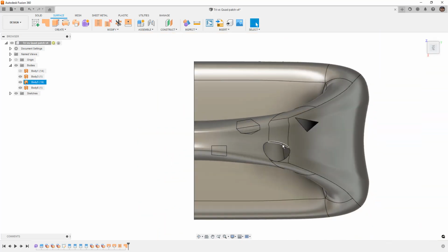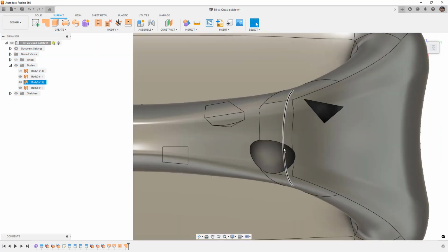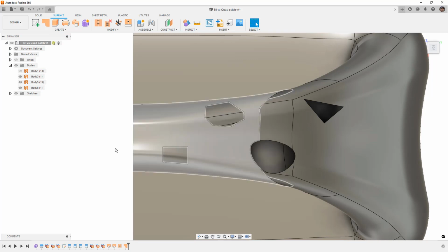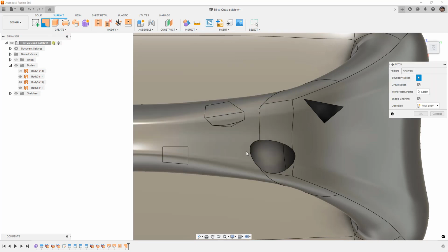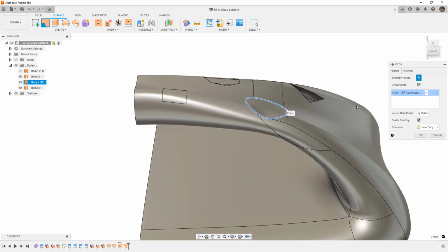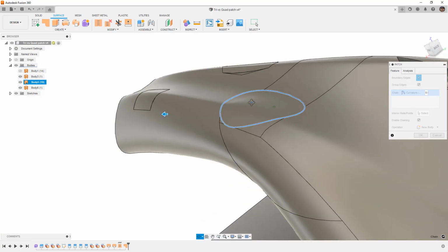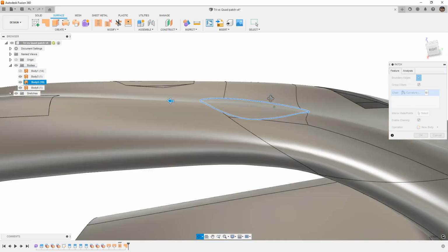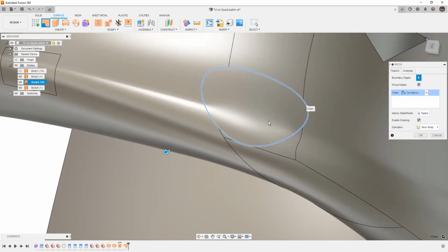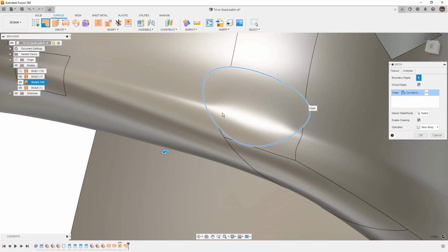Next, we're going to take a look at this edge. And this edge right here looks just like one smooth curvature continuous edge, which is true. However, patch still has the same problems with this. If we are going to use curvature continuity or tangency, it's going to give the same weight or the same amount of influence everywhere, which means in this case, you can see that crisp, clean edge is again disappearing.